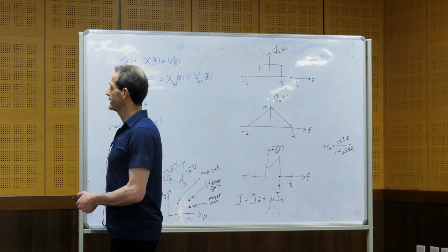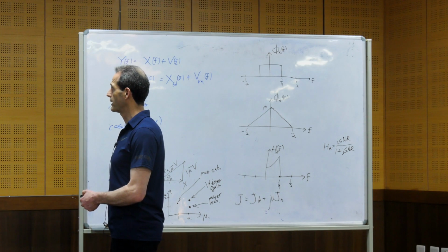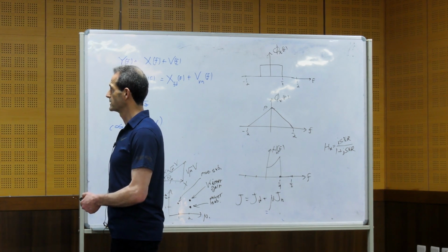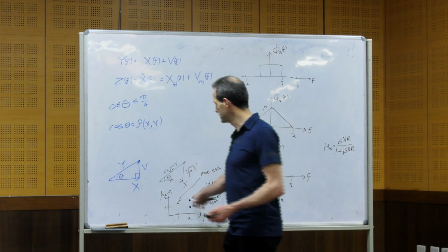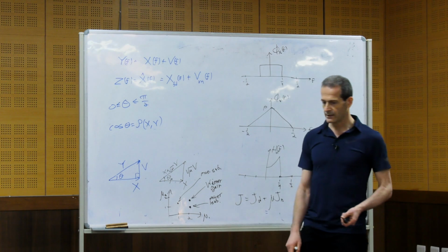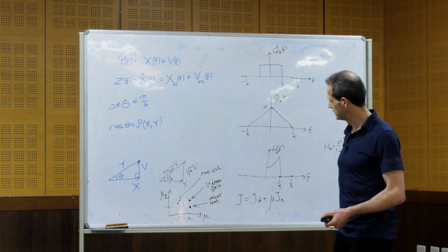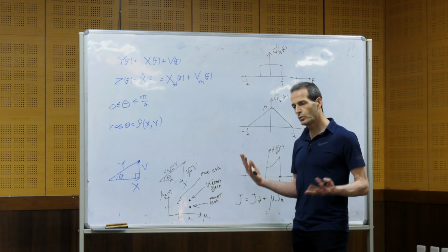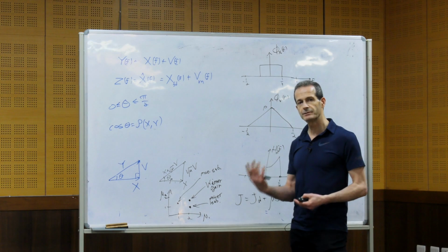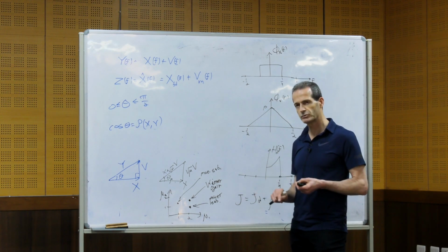Okay, so the noise reduction that is obtained with the magnitude subtraction is higher than the Wiener and higher than the power. But the distortion, you see, is also higher when the noise reduction is higher. And the nice thing is that you can choose different parameters, but also you can find what is power subtraction, how is it obtained.